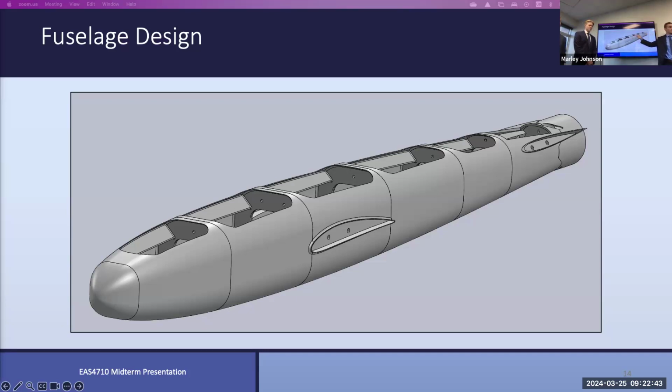Well, you don't have to; you could do it with a single fastener, closer to the longeron. I think I would prefer that. It's not ideal from a load path perspective to do it on the side. You can also do it with smart fasteners. We did weigh our fasteners and looked at the lowest ones we used last week, and we found it wasn't too bad, but it was under 50. Always the lighter the better.